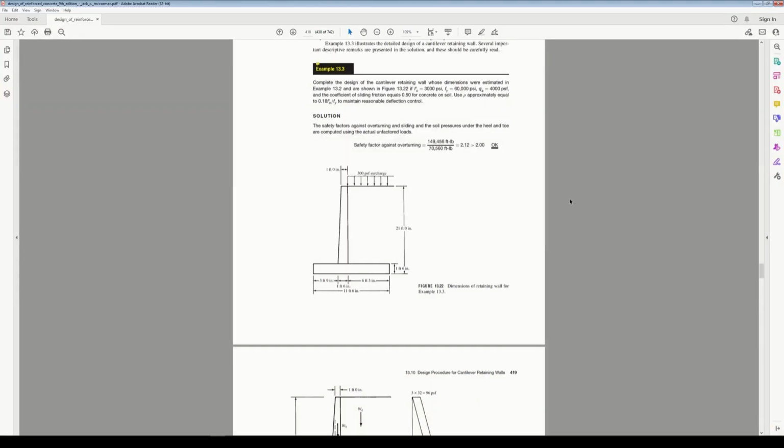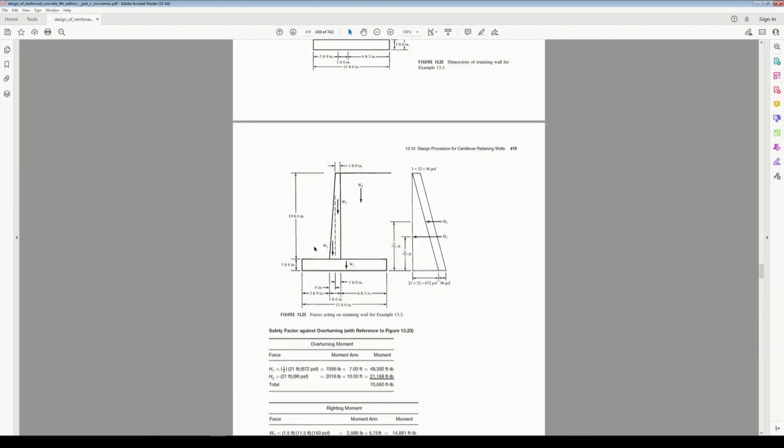Yes, it matches. So now we want to do the top of the footing so that we can draw a wall only from the top of here. So we will make a node, a vertical node, 1.5 feet above from here, and then another node, 19.5 feet from this node. I think this picture shows better, yes. So this one here will have 1.5 feet above, and then 19.5.